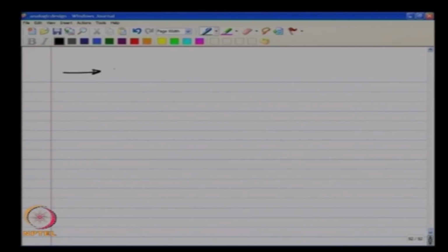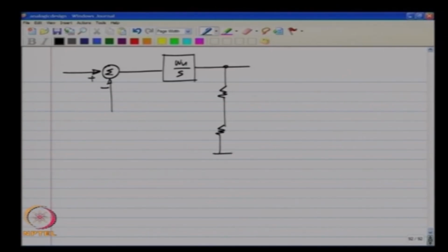So, while modeling the delay, I will use the Laplace transform here. While modeling the delay, what I had done was to insert an ideal delay e raised to minus s times T d. Now, what I have to do is not this ideal delay, but some extra factor that has all kinds of poles and zeros.